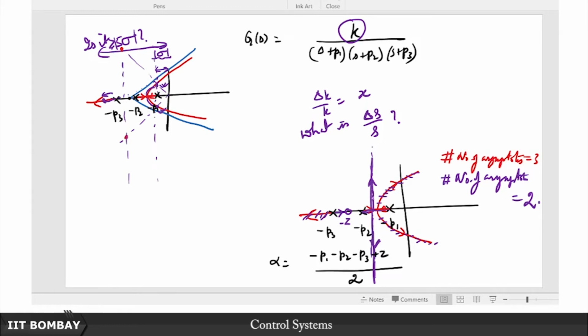So this is now the compensated root locus, and immediately you see, if you draw the constant zeta line, without the 0, you are forced to place your closed loop poles at that particular value of zeta here. But now, with the 0, you can now place your pole here. Notice that even if this centroid was somewhere here, because the angle has now changed, this was actually a 60 degree angle that this asymptote was making earlier, now this asymptote is making a 90 degree angle. So there is a net shift at least to the left, right?